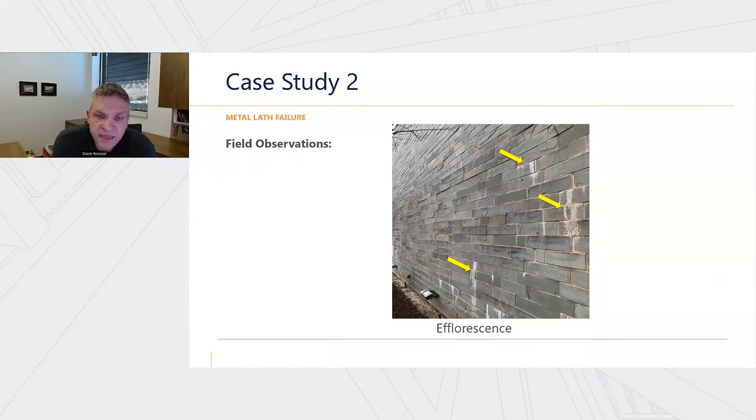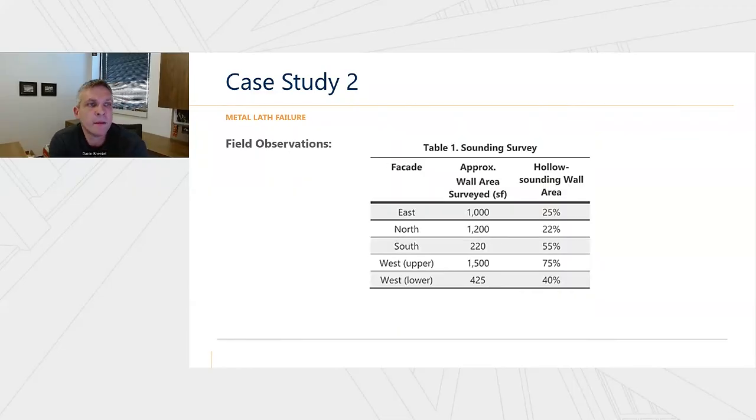That basically occurs when water can enter between the joints, get into the backup mortar, strip water-soluble components out of the cementitious materials in that mortar, evaporate, transport those materials back to the surface, and leave behind a salty white-colored residue.